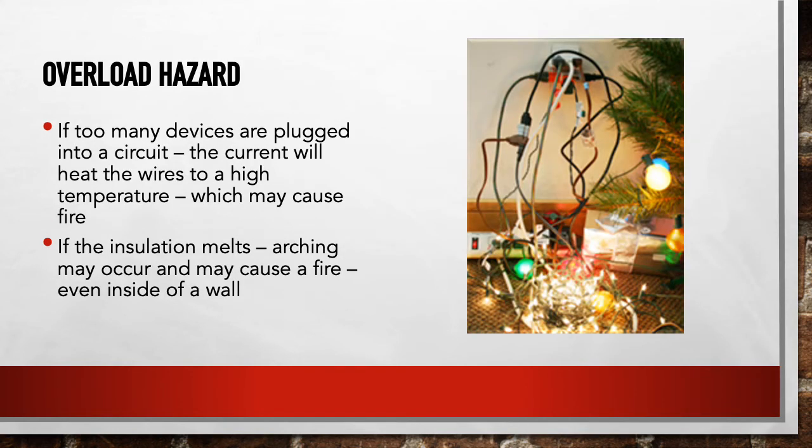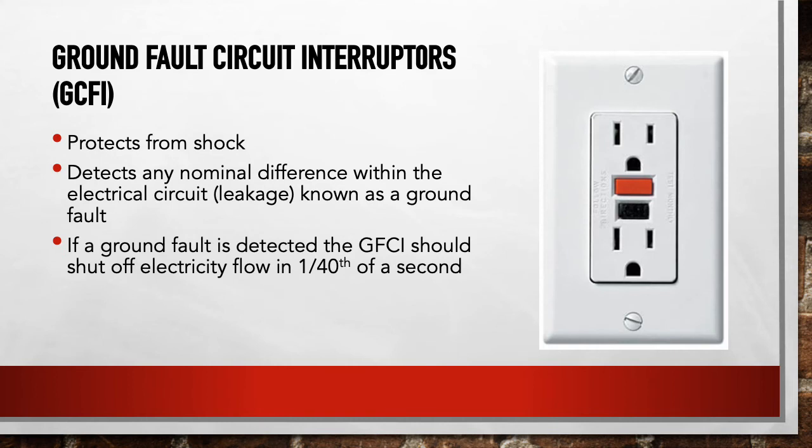So overload hazards. This is something our parents told us about when we were a kid. You don't want 50 things plugged into one outlet. What can happen is, if the circuit doesn't trip, things heat up too much, whether it's the plugs or the receptacle, and that heat can burn through the insulation and then cause an arc as well as a fire. And we've all smelled kind of the heated electrical insulators before.